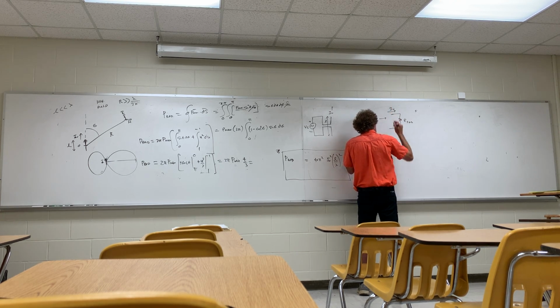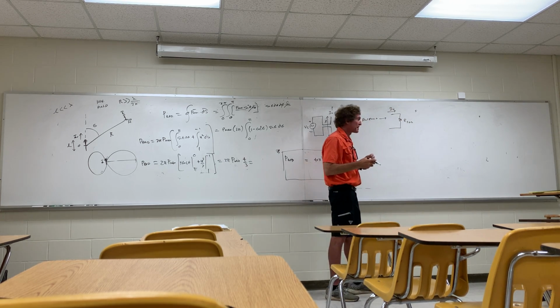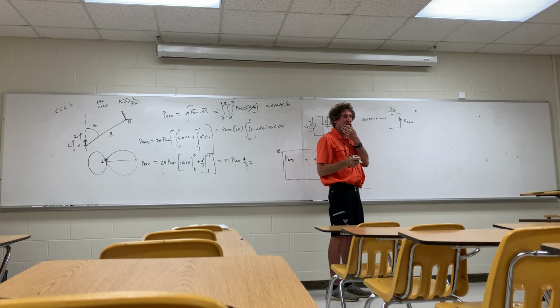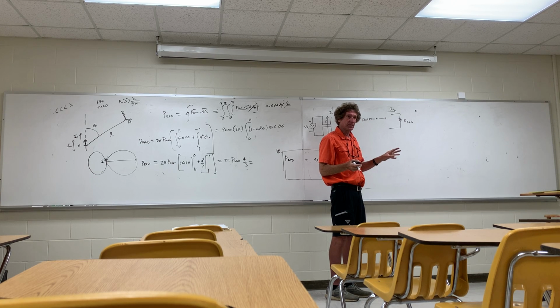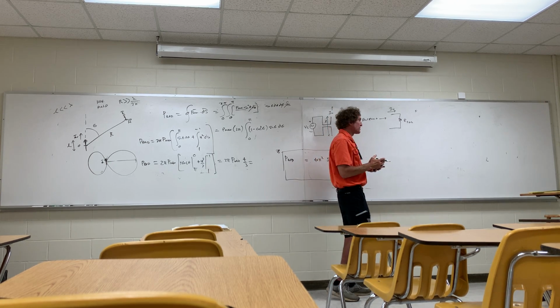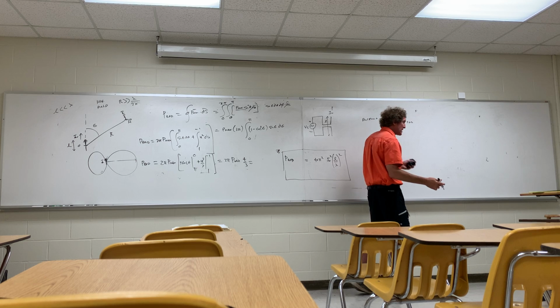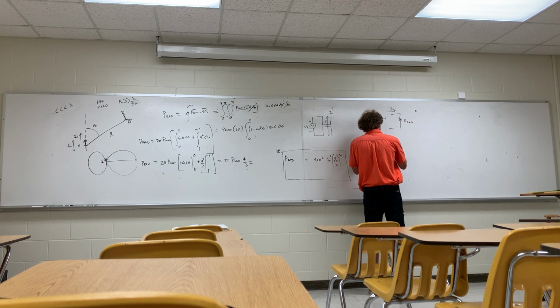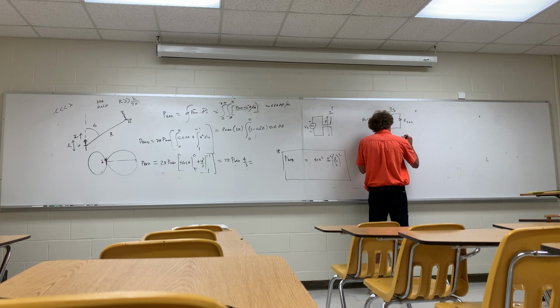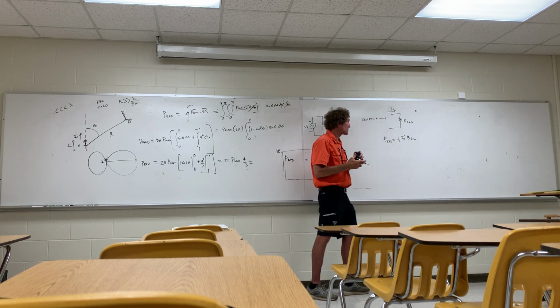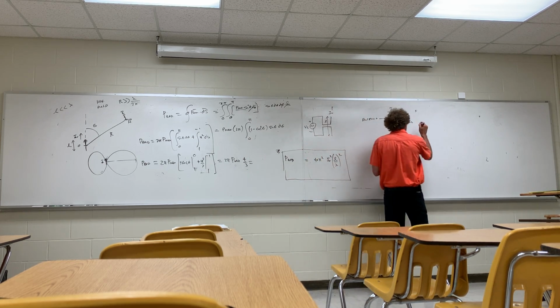There's a current I naught going into R rad. Now this is a standard type of thing you see in circuits. Remember, this is a time varying field, we're in the phasor domain. So the power dissipated by a resistor would be 1/2 times I naught squared times R, and this would be R rad. You all follow me? Now this is called radiation resistance.